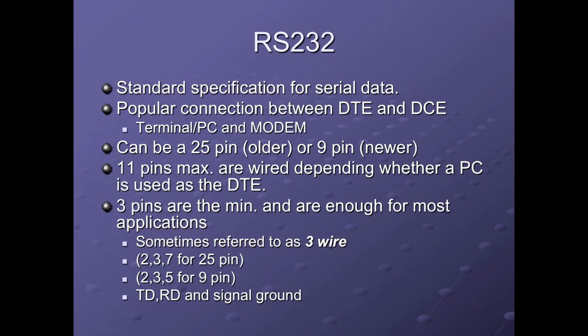Way back in its day, the RS-232 connection was designed to be used between a terminal and a DCE, or a terminal and a modem. Originally it was 25 pins. Because the terminals or devices were a lot dumber back then, or less sophisticated, they required more traffic signals, or handshaking signals. There'd have to be signals involved in the connection that said, hey, wait, stop sending data, my buffer is full, I need some time to process it, or I'm not ready to receive your data yet, I'm still initializing, or whatever.